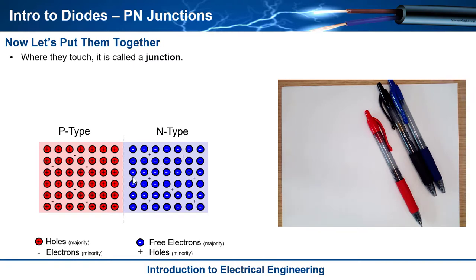And a battery does have this concept of positive and negative, but a battery is an active source. So we had anion, cation materials, and then an electrolyte, and it worked a lot differently. But it is the same in that when we have this p-type and n-type material, current can only flow one way. What we're trying to do is take these electrons and move them to the left, and then correspondingly the holes will move to the right. So this p-n structure is inherently dictating that the electrons flow this way, right to left, and then the current will flow left to right.